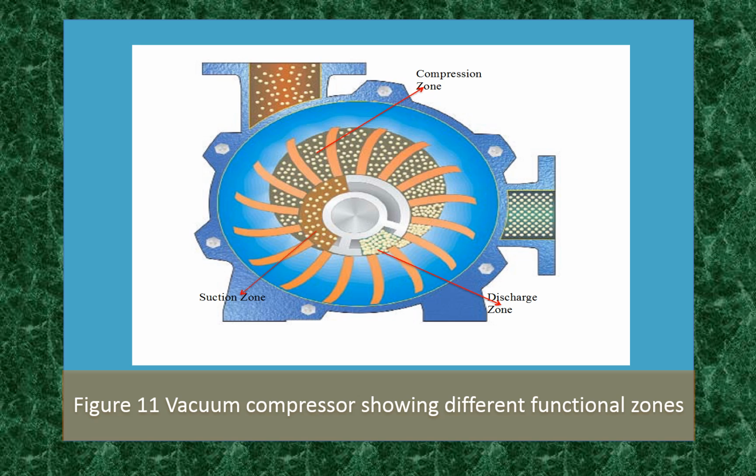A liquid ring pump has an impeller with blades attached to the center hub, located in a cylindrical body but offset from the center, that is eccentrically mounted. When the pump starts, the impeller swings the liquid sealant by centrifugal force to the outside walls of the body, forming a ring of liquid at the outside walls of the body.